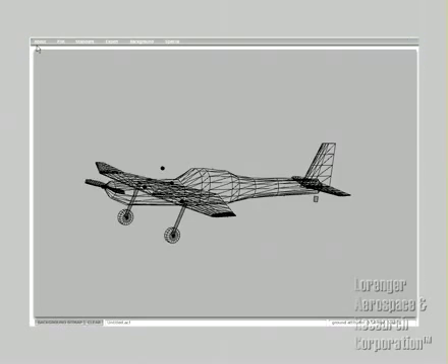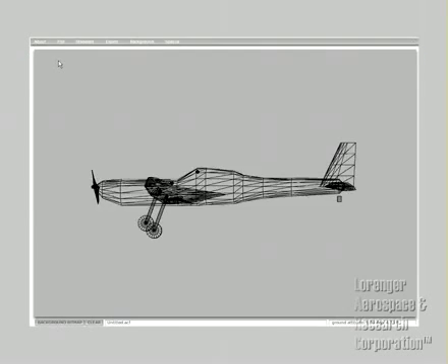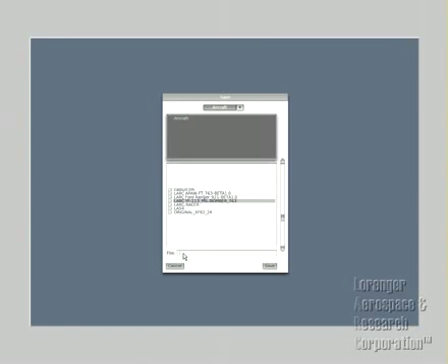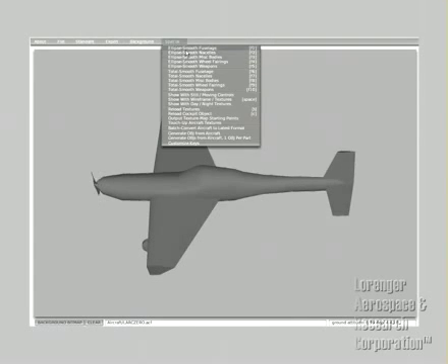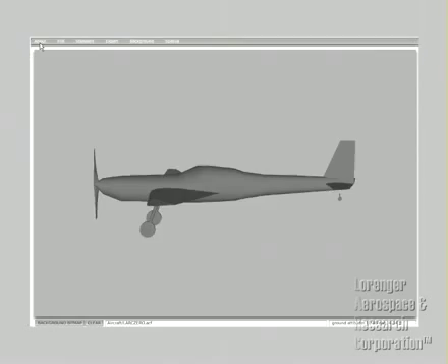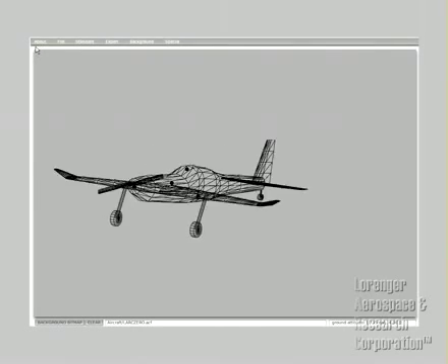Okay, center of gravity, make sure you put this near your mean aerodynamic center, MAC. That's typically 25% of chord. The true aspect ratio. It's really hard to do that with X-Plane because X-Plane actually calculates engine weights, and if you get really funky with weapons and weapon objects that have their own weights, you can really throw the CG off. Also by adding fuel in the wings, which are a little further aft, but more on that later.